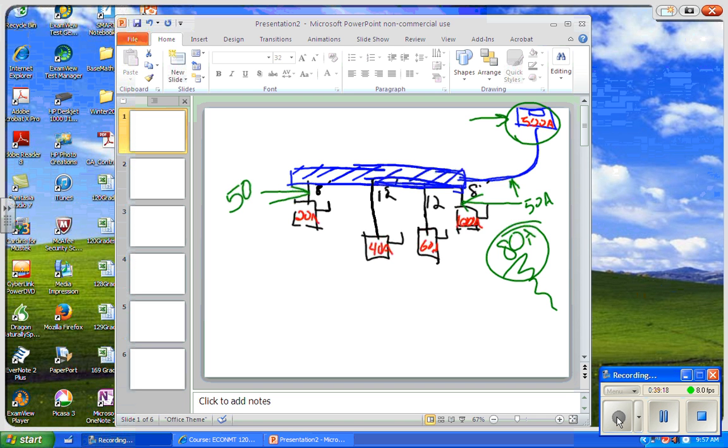1/3 of 1,000 amps would be 333. So half of 333, is that it? Maybe? How much is it? 166.67 amps. Let's call that 167 amps. Next higher amp, right? So that means that the wires that go to these disconnects, even though the load is less than 40 amps and less than 60 amps, in both cases, we're going to have to take wire to those that will carry at least 167 amps. And that's the 25-foot tap rule.